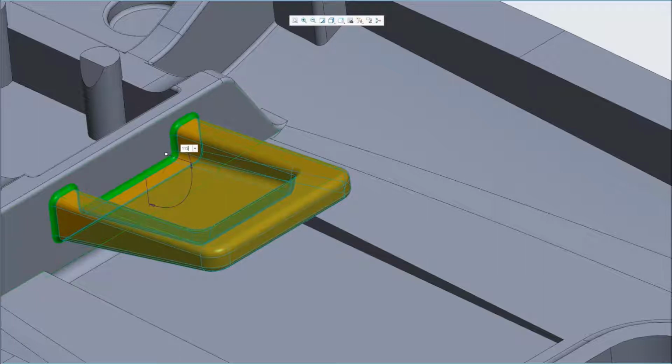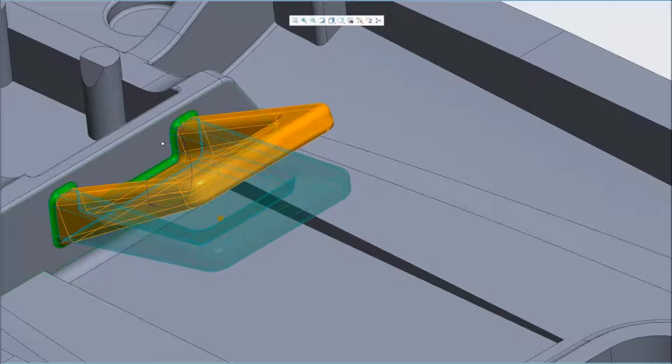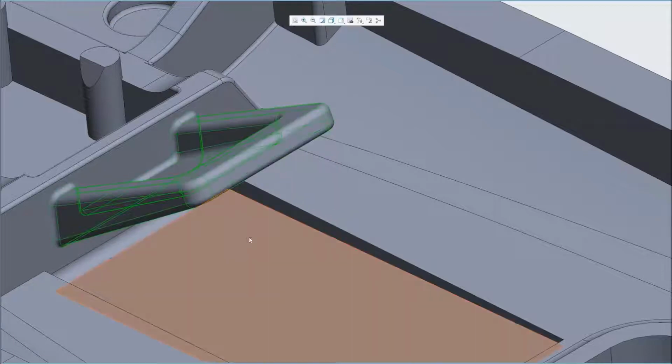So again, instead of having to recreate this entire assembly, this entire model from scratch inside of Creo, I can just modify the existing SolidWorks model that's converted, right? Modify that geometry to 115 courtesy of flexible modeling, and I can hit OK, and Creo regenerates the geometry, and now that's happy, right?